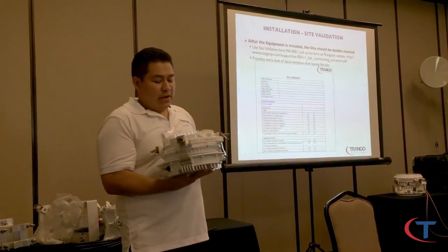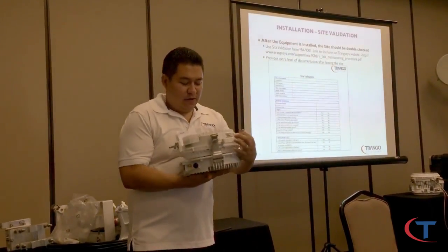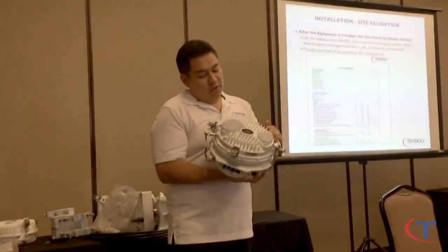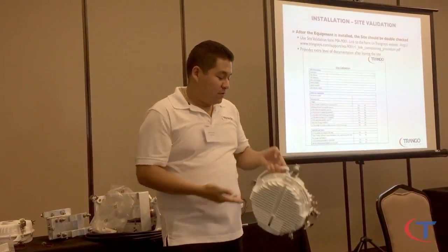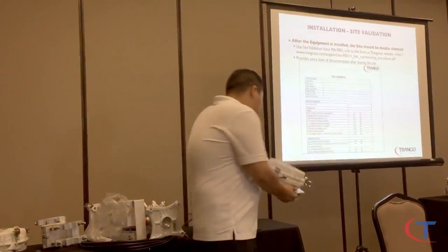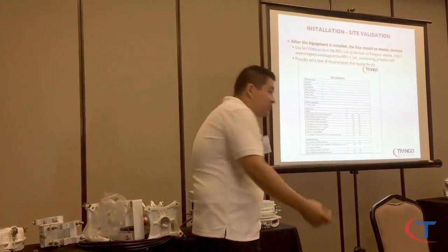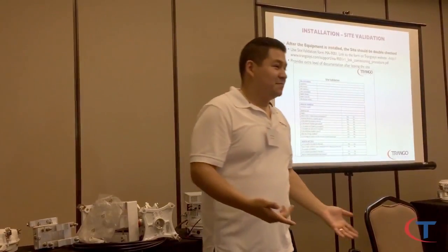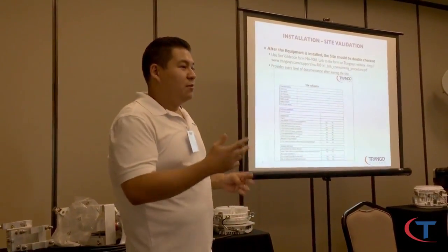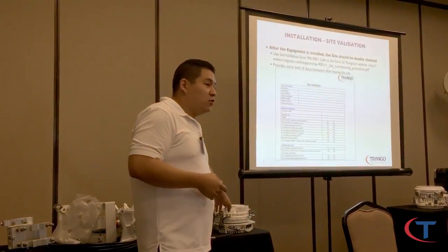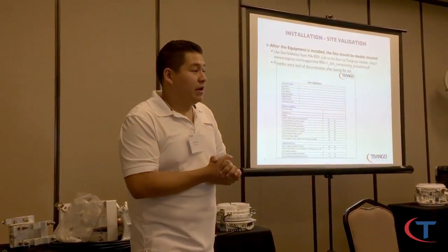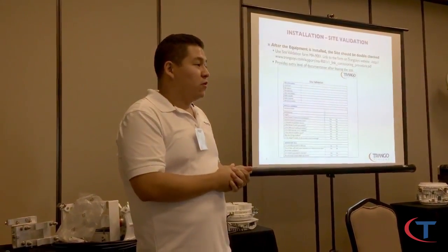Yeah. Now, inside of here, when you get your radio, you're gonna have a little packet with dielectric grease and, by a street name we know, a finger condom. Okay? This is because you're gonna put the grease in the actual ODU before you stick it on the back of the antenna or the combiner. This is for waterproofing the connection as well.